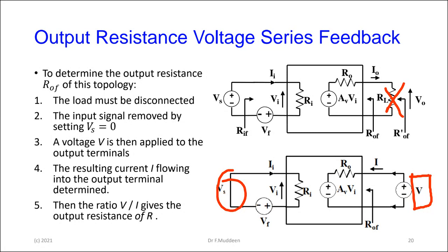This is kind of like when you're doing electrical wiring, for instance. I don't know if you all had a chance to do that, but when you set up the wiring, there are things like ground testing that you do. You're checking to make sure, of course, that the line and the neutral are not connected to each other, and that the ground is continuous all the way through.